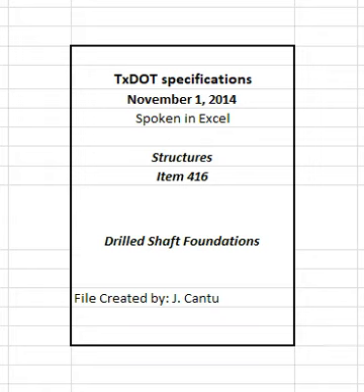Keep the tremie full of concrete and well submerged in the previously placed concrete at all times if using a tremie. Raise the tremie as necessary to maintain the free flow of concrete and the stability of any casing used. Keep the discharge tube submerged in the previously placed concrete at all times if using a pump. Place additional concrete to ensure the removal of any contaminated concrete at the top of the shaft. Allow the top portion of concrete to flush completely from the hole at the completion of the pour until there is no evidence of slurry or water contamination.